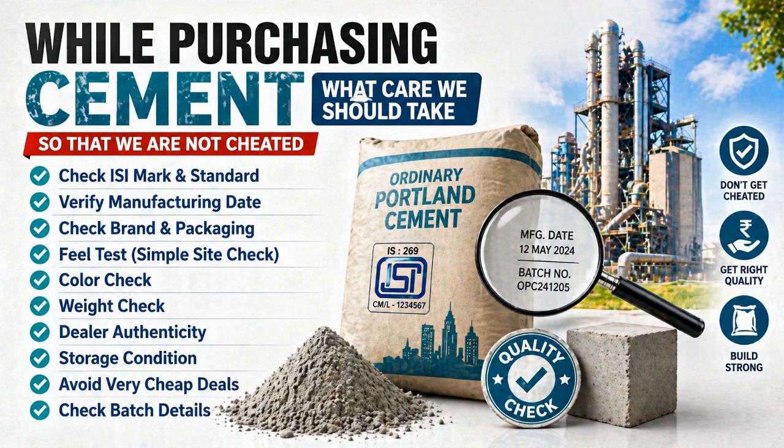To ensure purchasing good quality cement, always check that the bag carries a valid ISI mark from the Bureau of Indian Standards along with the correct IS code, IS 269 or 8112 or 12269, depending on the cement grade. Verify the manufacturing date and ensure the cement is fresh, preferably less than 3 months old, as strength reduces over time. Always buy from reputed brands and check that the bag is properly sealed without signs of tampering.